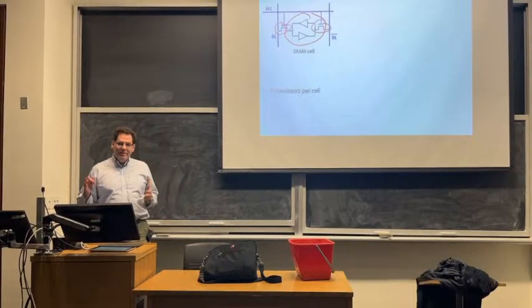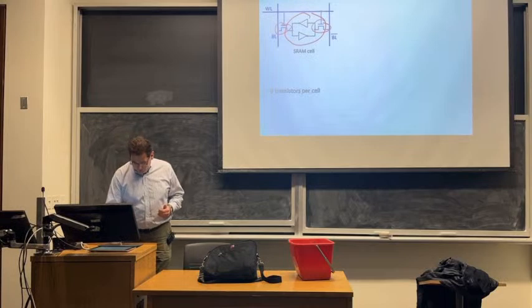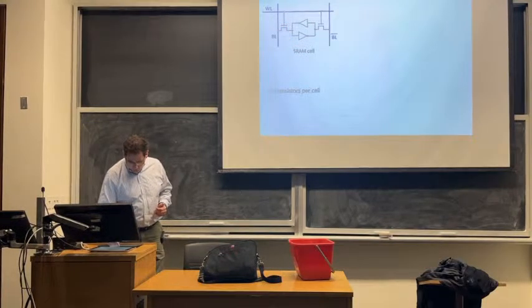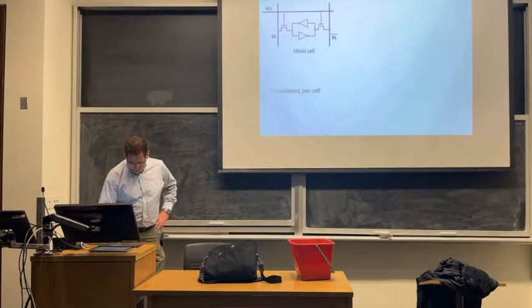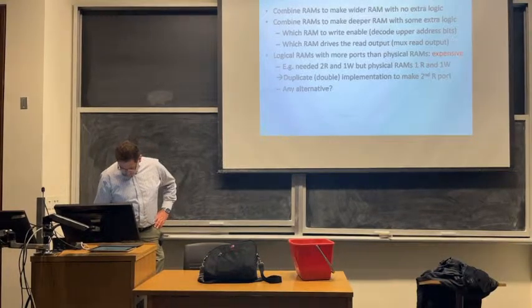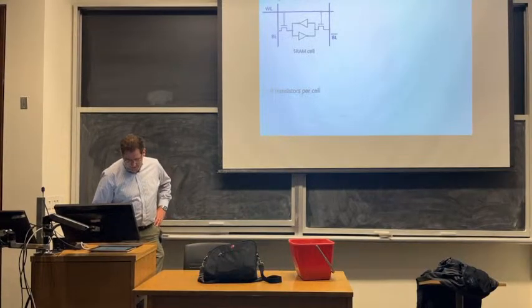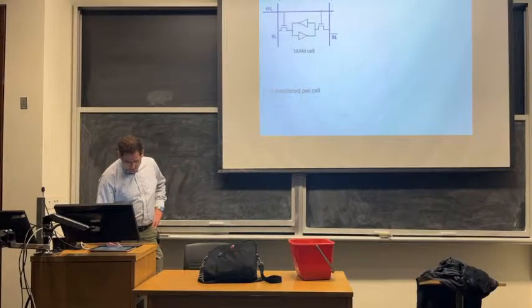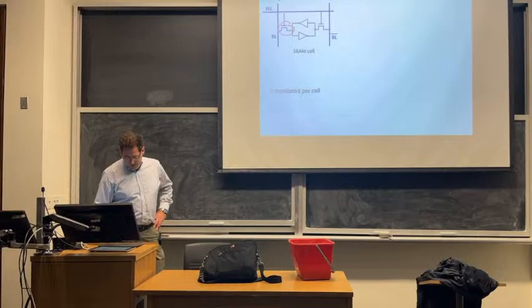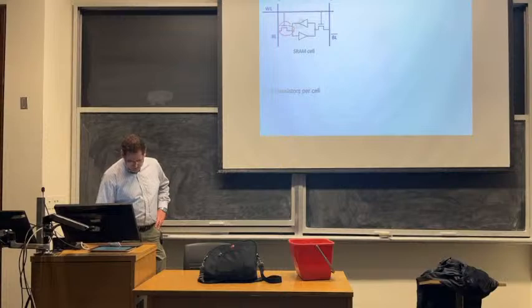I talked about this a bit earlier. SRAM design is actually kind of tricky. You have to design the pull-ups on these inverters to be weak enough that whichever side has a 0 wins. So if I want to write a 0 into this cell, I put a 0 here and a 1 here. And the idea is that this 0 pulls this node low enough that it is able to overpower this inverter. This node goes low, so that node goes high, and now this inverter stops fighting.